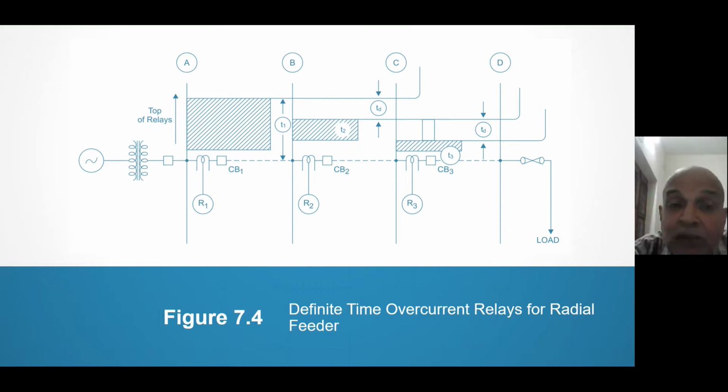And another thing, if the line is too short, this is the problem of ZS by ZL ratio. So it is not only a problem for the last section, it can be a problem for the first section also. Say Ukai hydro to Ukai thermal is a 6 kilometer line. There you cannot use instantaneous overcurrent relay because 6 kilometers cannot give the accuracy for an instantaneous overcurrent relay. So that is the reason why time discrimination, which we have started talking about, is useless. This also cannot be used for transmission line protection.